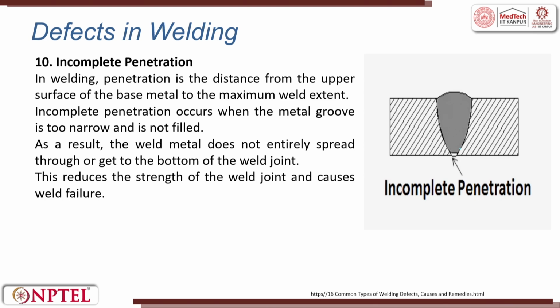There is also a possibility of incomplete penetration. When we do edge preparation, if the gap is too small and air gets locked in it, this air tries to prevent the weld metal from flowing. That is called incomplete penetration.